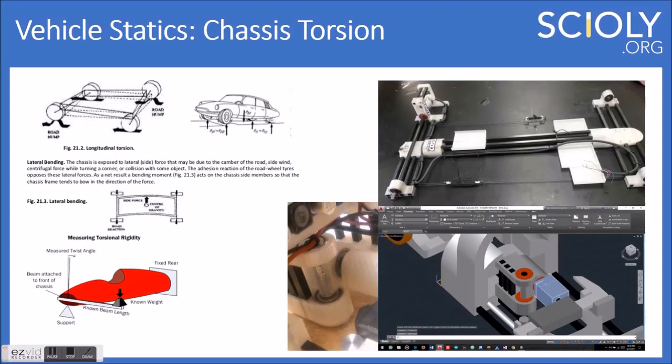And as you can see, with this carbon fiber frame that we implemented, it actually took care of a lot of the torsional parts. It was able to just twist based on the road slightly and compensate for any imperfections. Whereas if you had just used a piece of plywood as your entire frame, it wouldn't be able to do that unless you had some sort of suspension built in. And suspension can be quite tricky to implement properly, and it can give you a lot more problems in other areas, although it is something I do wish I had looked into.